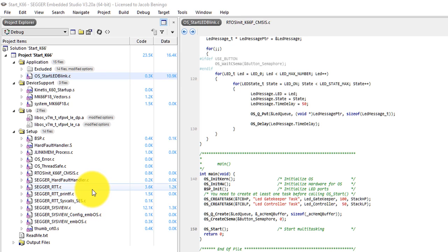Now the RTT is called real-time transfer, and this is the code that's going to very quickly and efficiently communicate up into our J-Trace device. And then we have a couple of libraries here for SystemView, which is going to help communicate context-specific information to the software as well. Now you can see here when we originally looked at this that, hey, our entire project